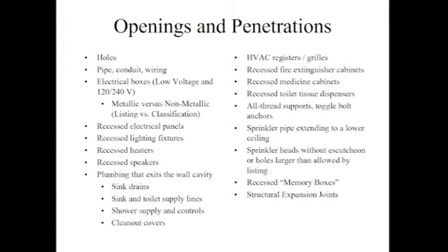And there are very specific processes or ways in which you need to patch holes in a rated assembly and/or fill them. And you can't just sort of, what we call scabbing, additional gypsum board over the hole and just screwing it into the gypboard, or even worse, gluing it onto the gypboard. The Gypsum Association, in their Fire Resistance Design Manual, talks about it, as well as they have their own white paper discussing how to appropriately fix or patch a hole on a fire rated wall or fire resistive construction, including a ceiling.